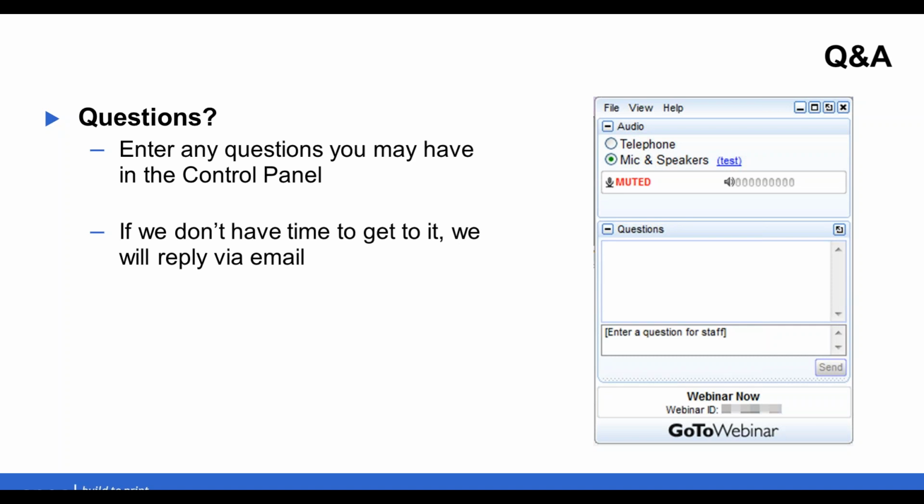It's a good question. First, you need to make sure that the assembly that the keypad mounts to is adequately sealed and was designed with sufficient ingress protection. Once that's been addressed, the next thing to consider would be to look at the volume of air trapped inside the keypad and compare that to the volume of air in the adjacent compartment. Then, if possible, you may be able to add maybe a 100 thou or so vent hole between the two compartments. That would allow pressure to equalize, and hopefully the keypad should be able to function as intended.